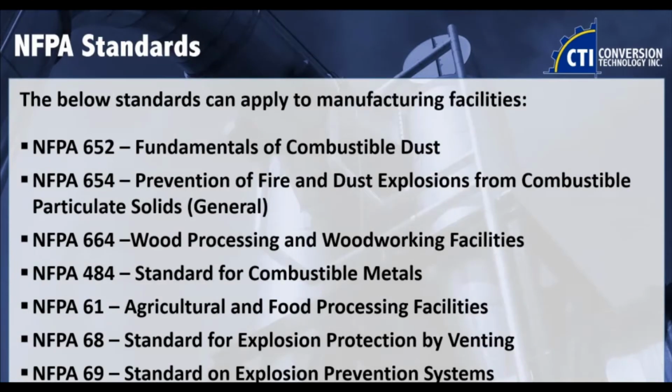Some of the specific combustible dust standards from NFPA. So you have NFPA 652, which is the fundamentals of combustible dust, that is the overarching standard that applies to all facilities with combustible dust. That is where you will find that deadline I had mentioned of September 7th, 2020, which is passed, for all facilities to conduct DHAs.